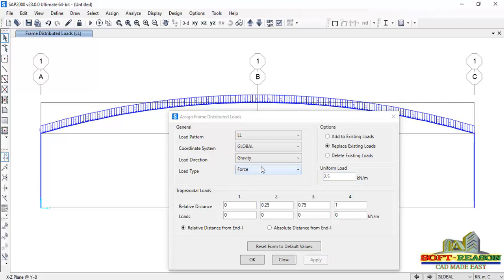The next load we are going to apply is the roof wind load. You select that, click on previous selections, and make sure it is selected. It is now selected. This is the previous selection. So this is 3.6. Click on apply.